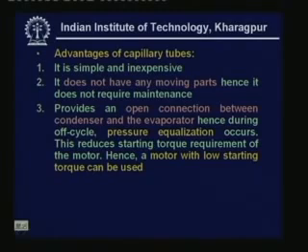When the system is off, that means when the compressor is not running, the condenser pressure is much higher than the evaporator pressure. So pressure equalization takes place through the capillary tube, because a capillary tube is nothing but an open tube. So finally you find that during the off condition, if sufficient time is allowed, the entire system pressure will be the same. So when the compressor starts after the off condition, it has to start against the same head back pressure. That means it does not require a lot of starting torque to start, so you can use low starting torque motors.